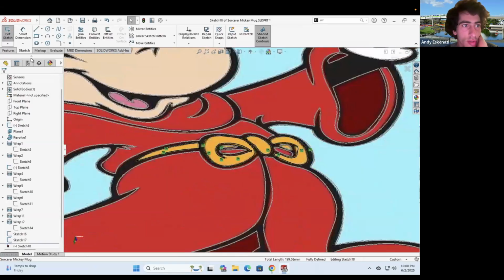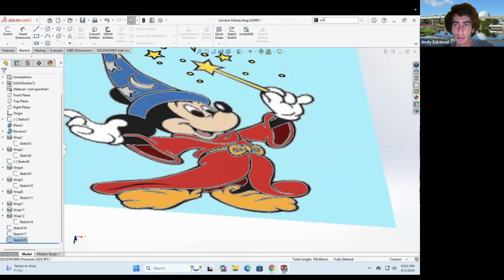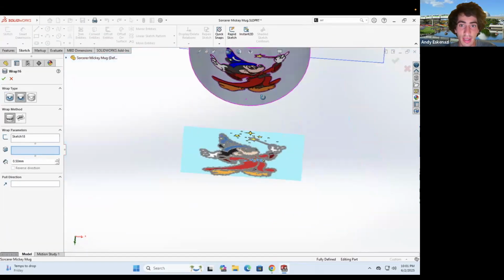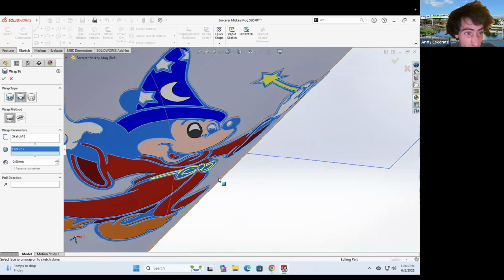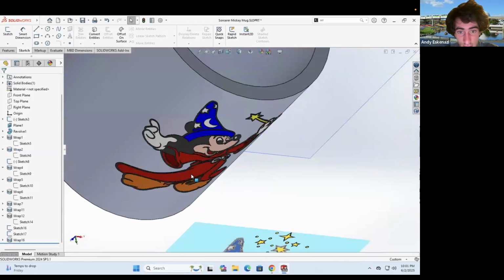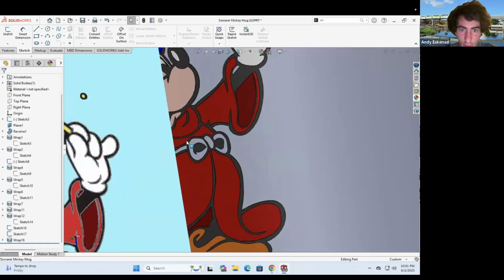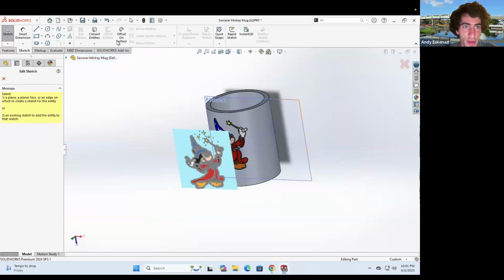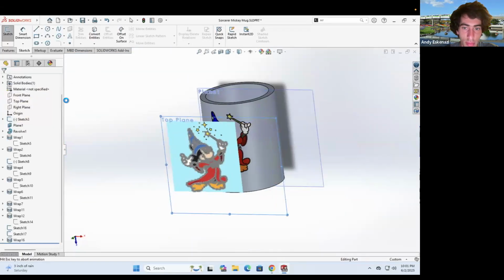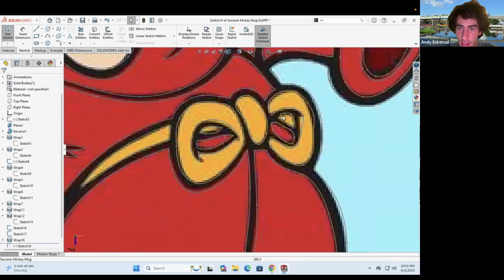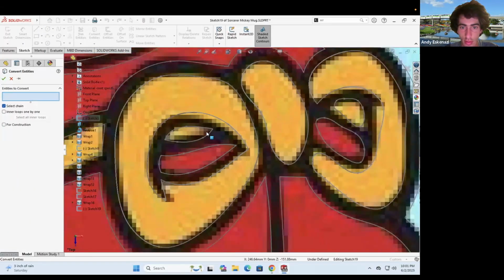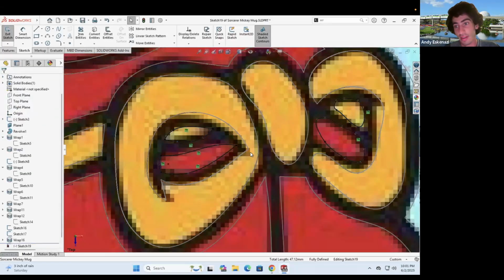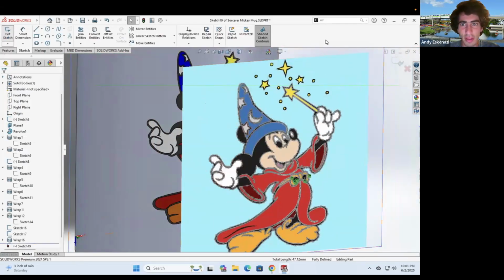Good. So I'm gonna go here to exit, and now we'll go to wrap. And technically, if I were to click on that build, it might work. Let's see. Okay, good. Inwards, terrific, just like that. Okay, very good. And now let's do one last sketch on the top plane. And I'm gonna select all of those circles in there. So convert, not that point. I'll say 1, 2, 3, 4. They're not the nicest circles, but they are all right.